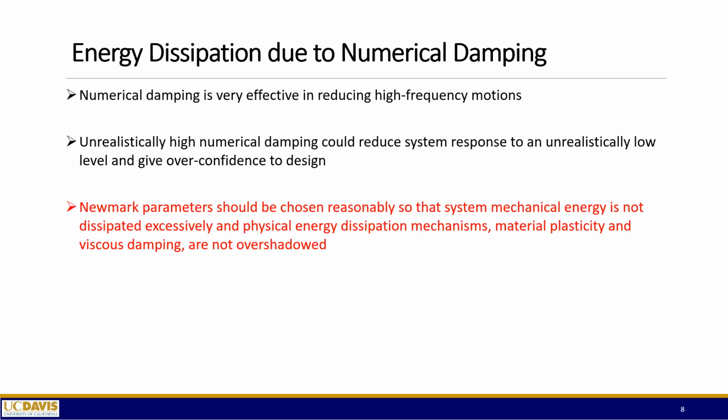So a good engineer, a good modeler, will do a small sensitivity study just to see what is the influence of numerical damping. And I know this takes more time, but it has to be done because the analyst or engineer has to understand the effects of numerical damping. And as you're saying here, you do not want to overshadow physical damping by numerical damping. So numerical damping is just there to keep it stable and to eat up a tiny bit of those high frequencies, but let the physics, the viscous and material damping, take care of the actual proper energy dissipation.